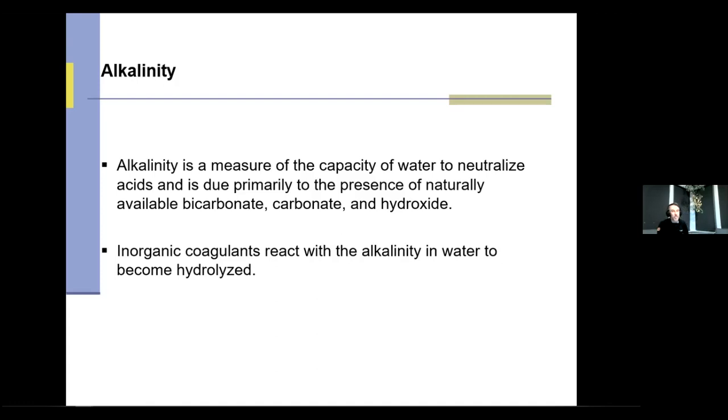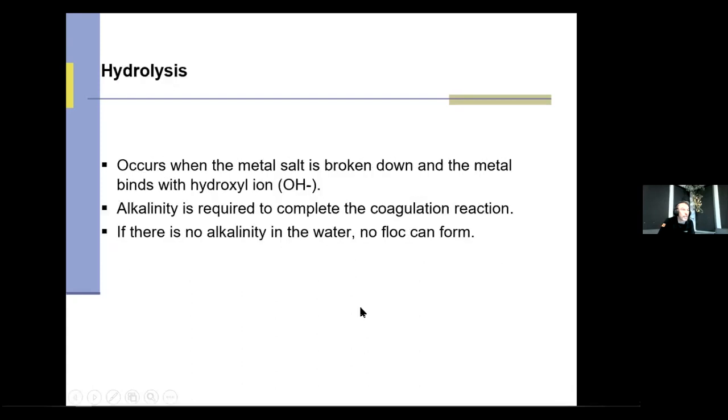It's like that sports car. You got to put gas in it. No gas, you ain't going nowhere. Same idea. Hydrolyzed is that word. So now that it's hydrolyzed, the metal salt's broken down, and the metal, in this case aluminum, binds with those hydroxyls, also called alkalinity. Then we're ready to go.